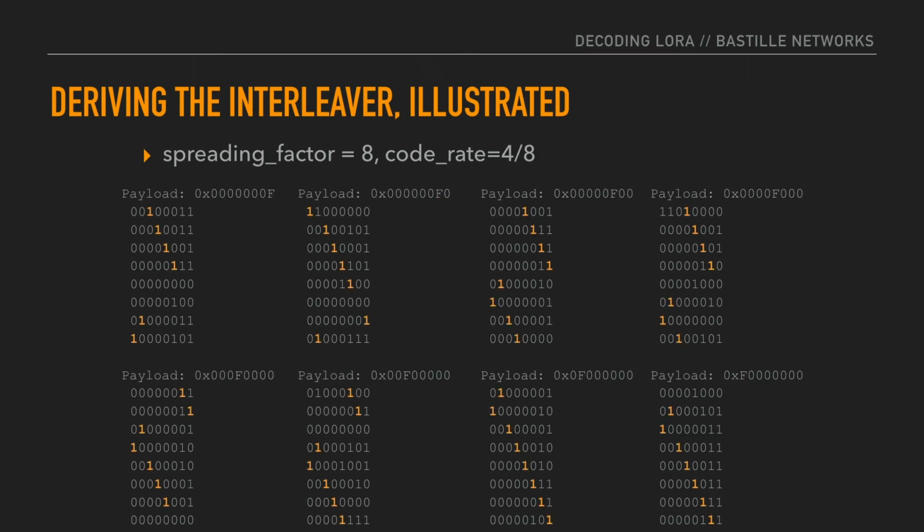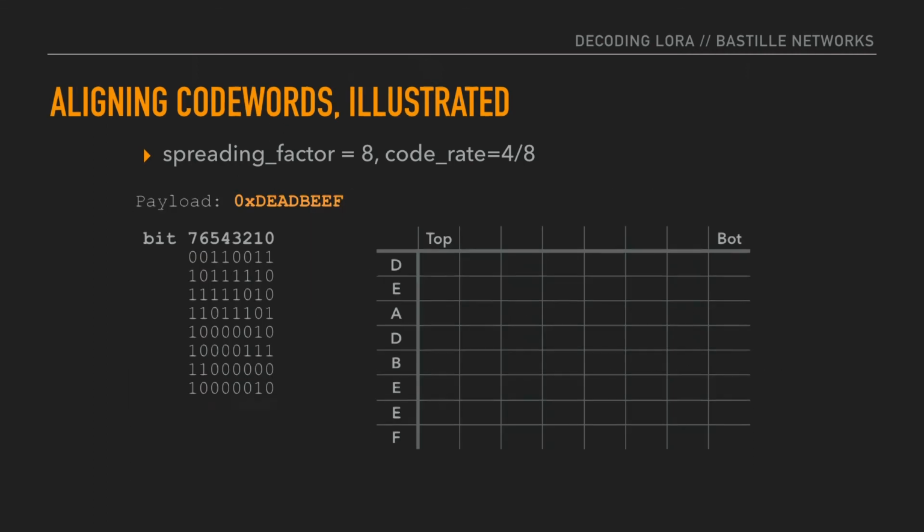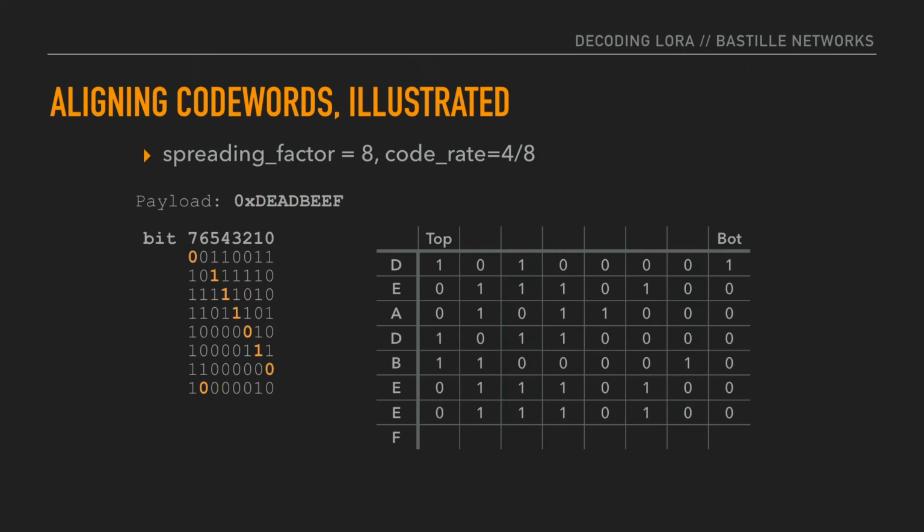Who sees it? I'll save you the trouble. Who sees it now? Look at the bottom row, second from the right, and you'll see the pattern. Basically, it's a diagonal interleaver, but the 2 most significant bits are flipped. So if we take this, we can start to map those diagonal positions into positions within a de-interleaved matrix. If we walk through all the different states and map those positions out with data that we know, we get this nice table.